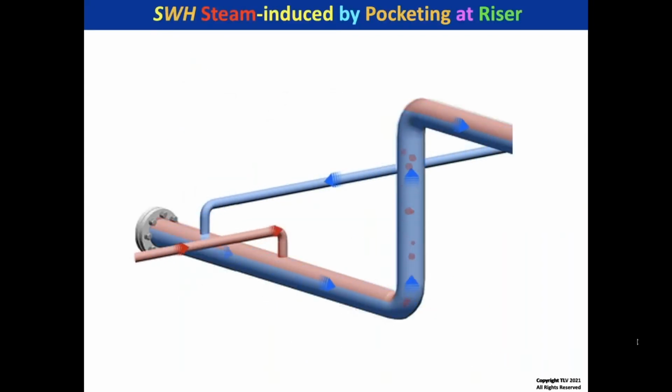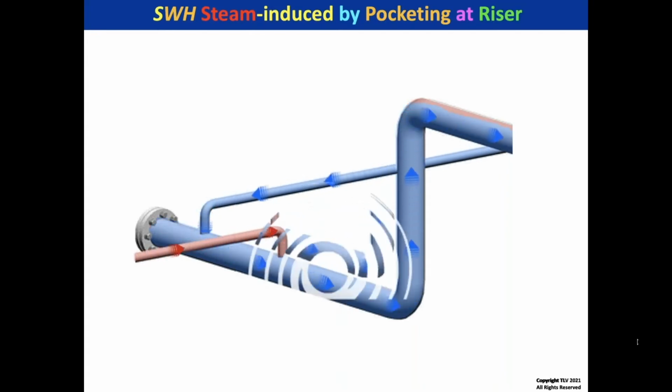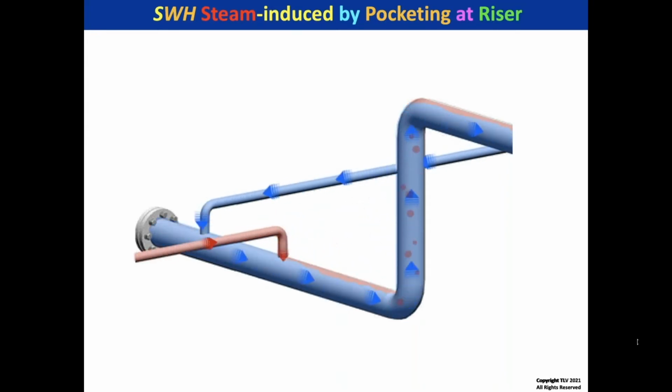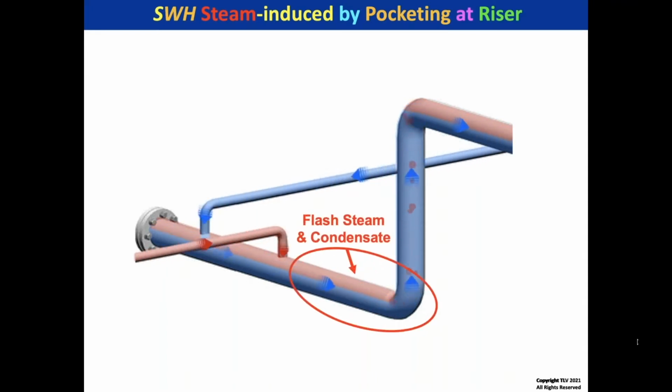People think steam lines are complex. Actually, they're relatively simple. I think they are. I think condensate lines are really complex. So take a look at this line. The first thing we're going to see is we have hot flashing condensate and biphase flow. Where the ellipse is, you'll see that you can get pockets of collapse like that one just did.